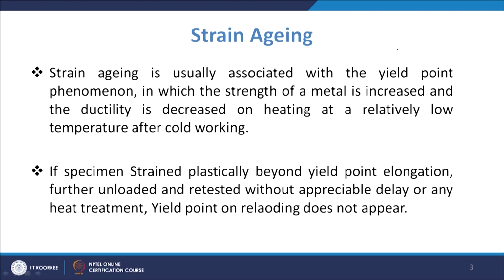Now, it was seen that when you are unloading it and then reloading it, the serrations or the yield drop, the yield point which was appearing, is normally not seen. So, once you have done that and then unloaded and reloaded without much delay, you do not see the appearance of the yield point.